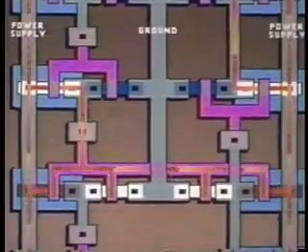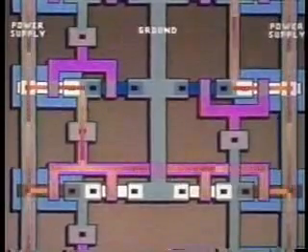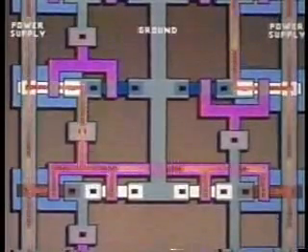It is possible to fabricate both P and N-channel transistors on the same wafer by doping sections of the wafer. This is known as complementary MOS, because a gate voltage which turns a P-channel transistor on turns an N-channel transistor off. To illustrate this complementary switching, a top view shows current flowing through the P-channel transistor in the upper left.